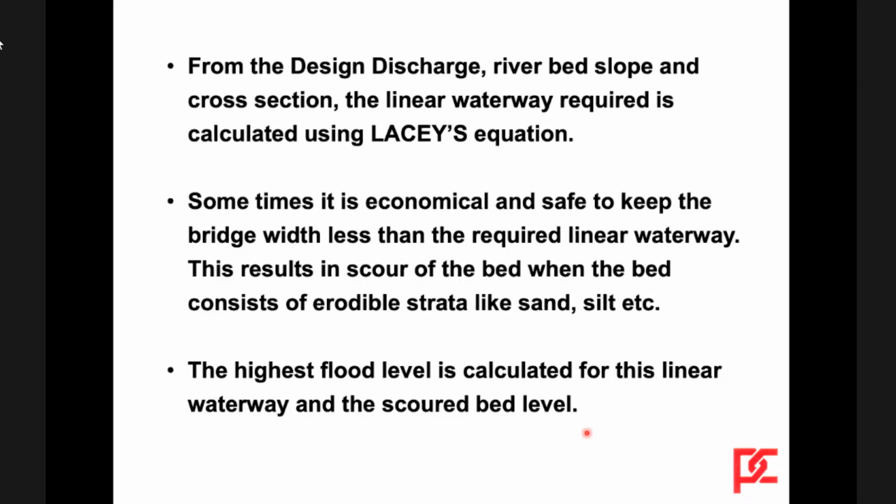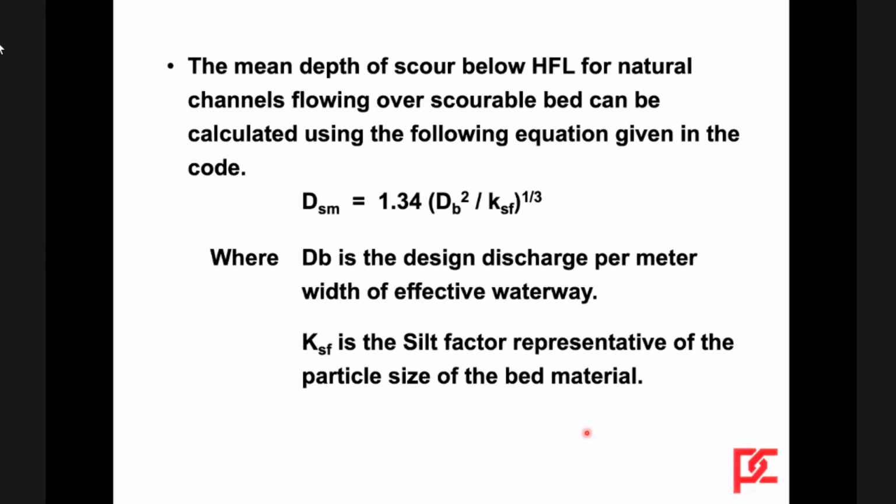This results in scour in the bed when the bed consists of erodible strata like sand, silts, etc. The highest flood level is calculated for this linear waterway and the scoured bed level. And after that, the depth of scour is calculated based on the formulas given in the code. The mean depth of scour below HFL for natural channels, that is dsm, is equal to this one.